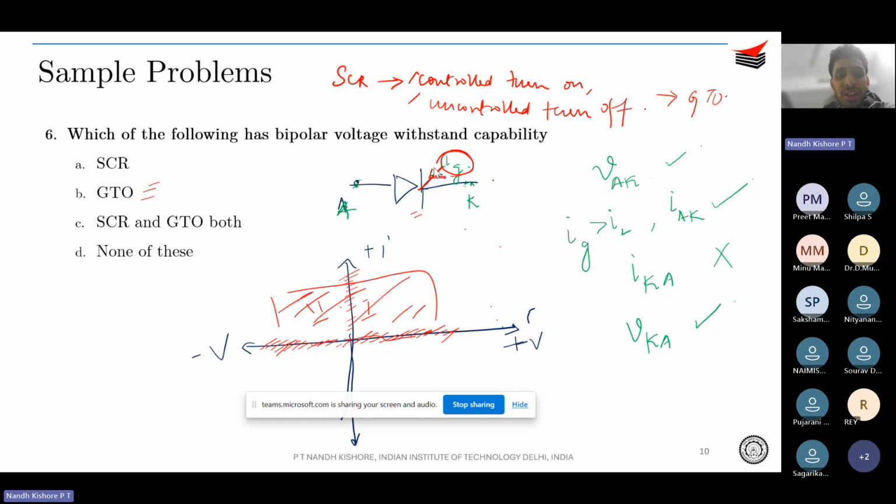You need to first apply a huge reverse voltage across the SCR, and make sure that your current goes below your holding current, IH we call it. This is a tedious process, and that's why we call the turn off semi-controlled or uncontrolled. So is it possible to use the gate current itself to turn off the device? The answer is yes, and it is possible with GTOs.